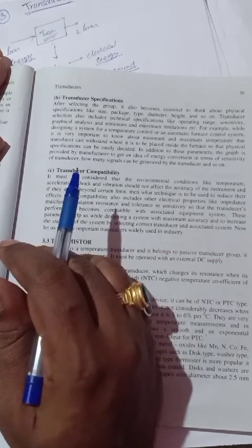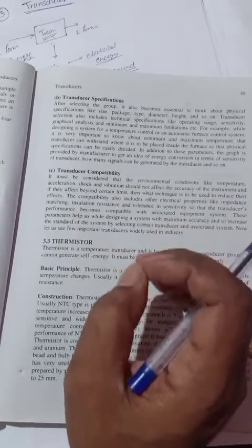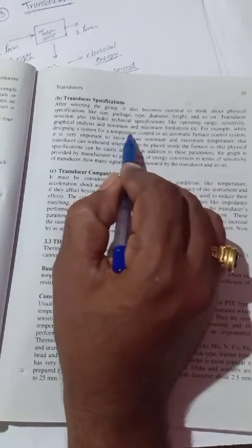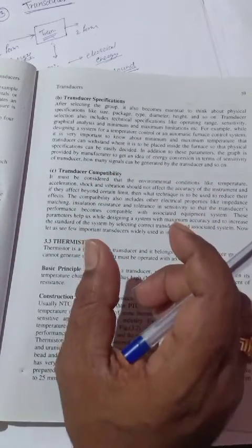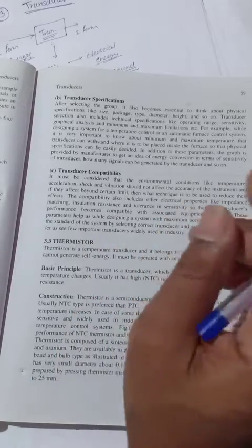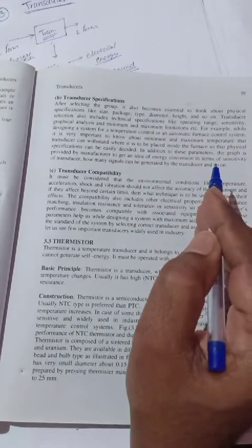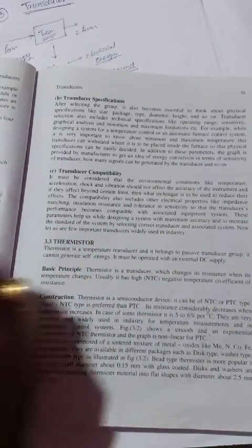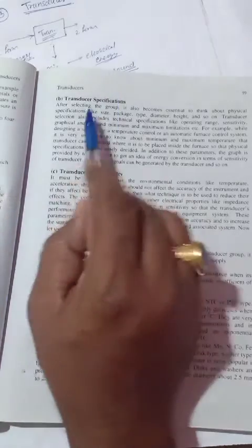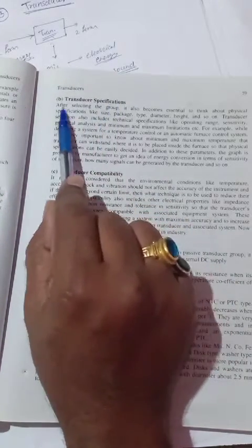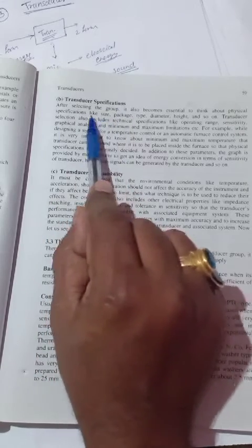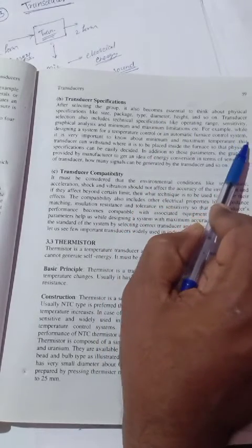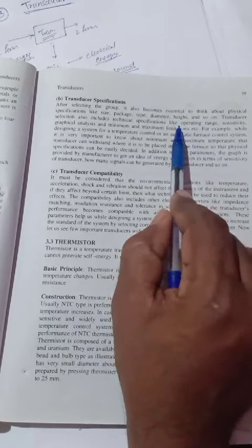And suppose there is some condition where you have to measure that particular quantity at a low temperature. In that case you have to select the temperature range of that transducer. If you use a transducer which is operated at high temperature to measure something at a low temperature, then it cannot give a perfect result. So you have to select a transducer by considering its specification. In that specification you have to consider the size, type, diameter, height, and so on. There may be some operating temperature range,